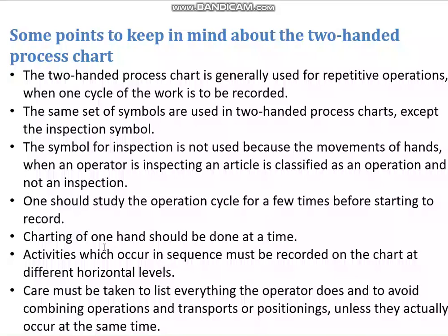And the charting of one hand should be done at a time. If the operator is working with both hands simultaneously, it won't be convenient to concentrate upon both hands. So it is better to concentrate on one hand and chart it out, and then afterwards focus on the other hand and again chart it out.